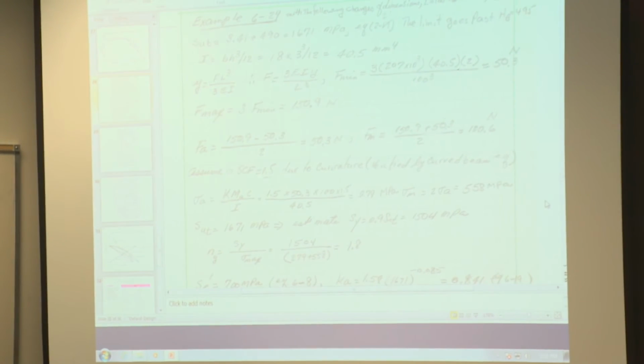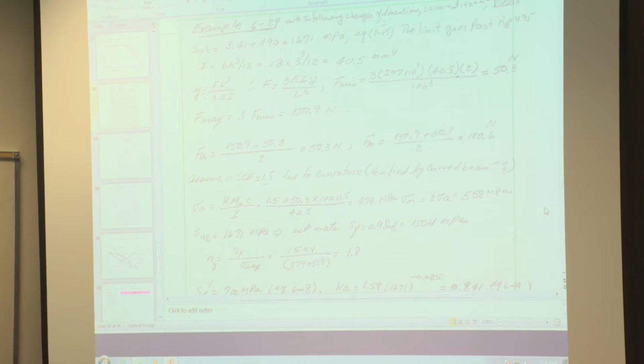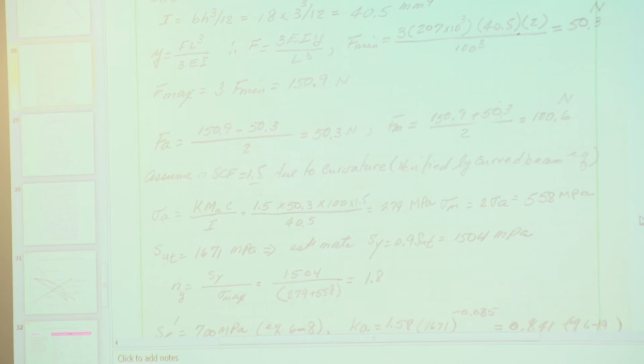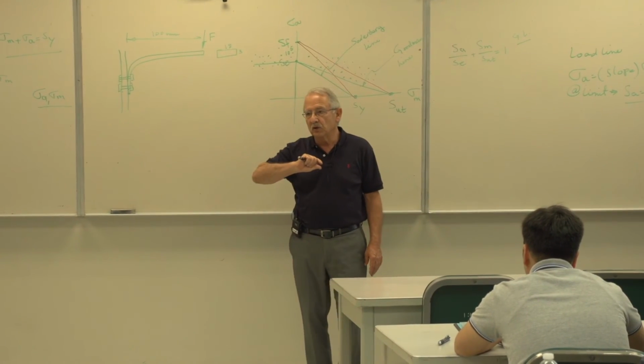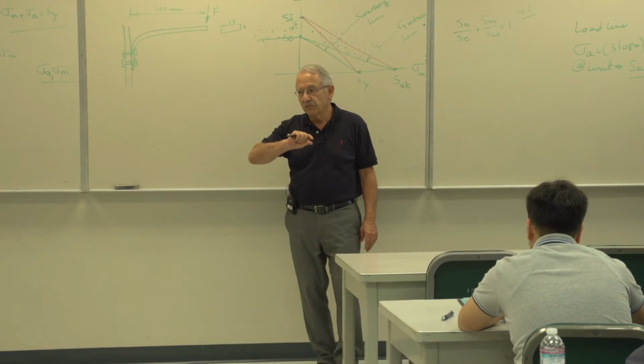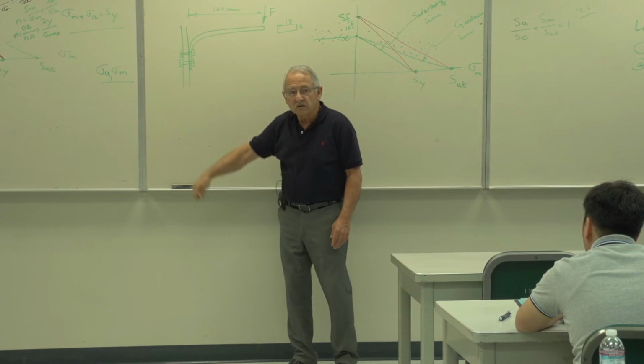And then it says to find the minimum and maximum load. The minimum load is what comes from shimmying under the bolts. In other words, what gives this cantilever beam a deflection of 2 millimeters initially. So deflection of 2 millimeters here on a cantilever beam.